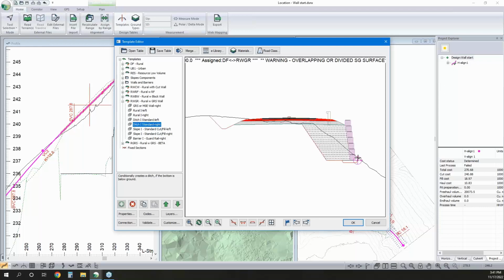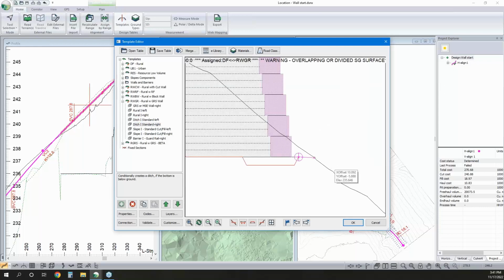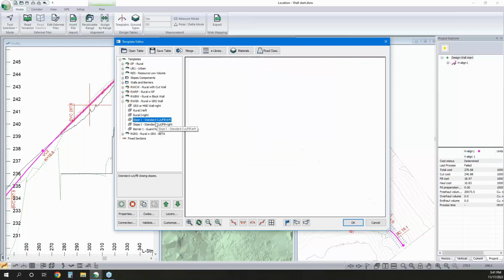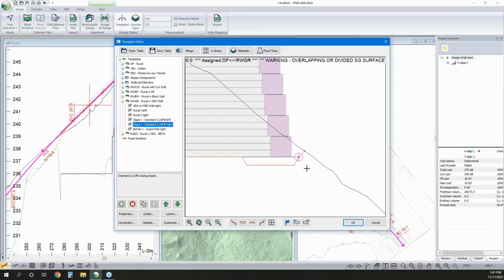So I've got a ditch being applied here, where if I didn't want that removed, I could tell it not to. So I can cycle through and see that that's being removed by my ditch component. I think there's some cases where you might want that just from a drainage standpoint where you daylight that out. So we can remove that, and now that cut slope is going back at whatever we have.